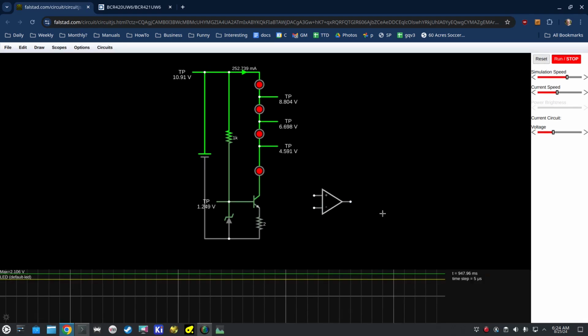Okay. So the way an op amp works is it senses the voltage on the negative without changing it. It senses the voltage on the top without changing it. When I say without changing it, it means little to no current is going in. And then it takes the voltage at the top, subtracts the voltage at the bottom, multiplies it by a very large number, like 100,000 or something like that, and that's what you see out the output.